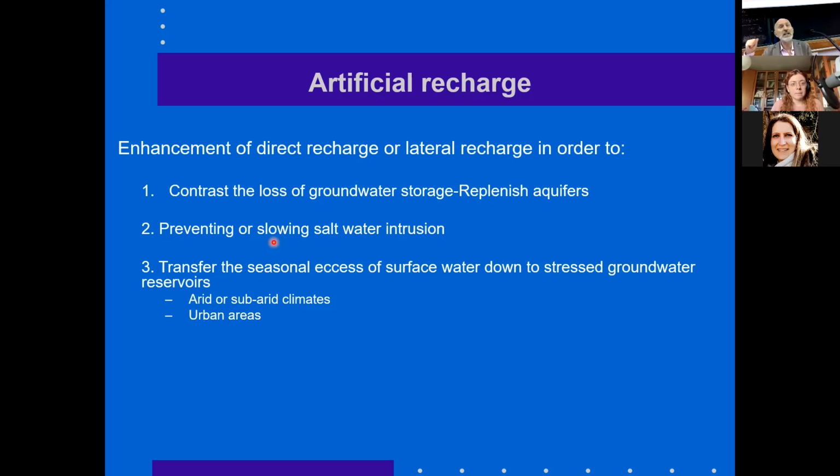But we know, we have seen in the preceding lesson, that in some places, also in Emilia-Romagna, you have an increase of rainfall intensity during the autumn, because you have many intense meteoric events, very concentrated in time and space. And they produce a lot of water, but most of this water is going to flow over the ground, not to infiltrate, because the quantity of water arriving in a very short time interval is very high. So you don't have a very effective transfer of water from the surface to the ground, because most of the water is flowing above the ground.